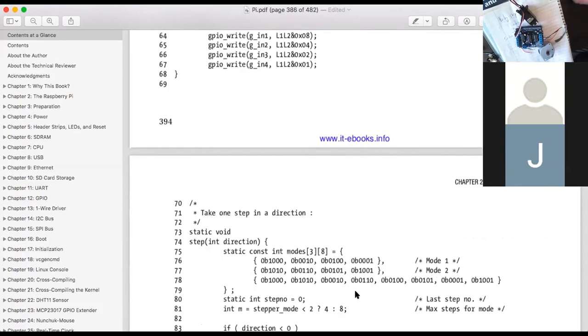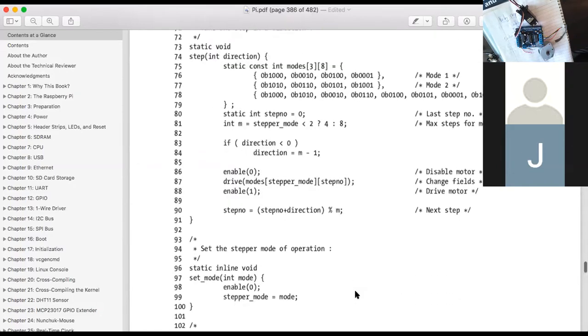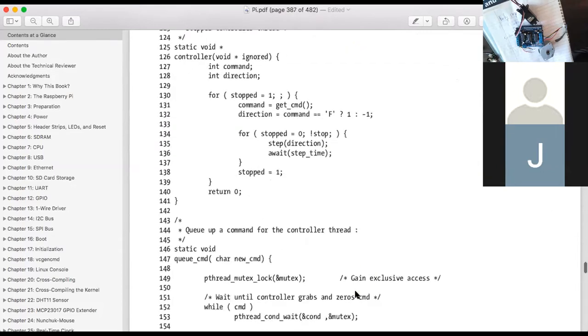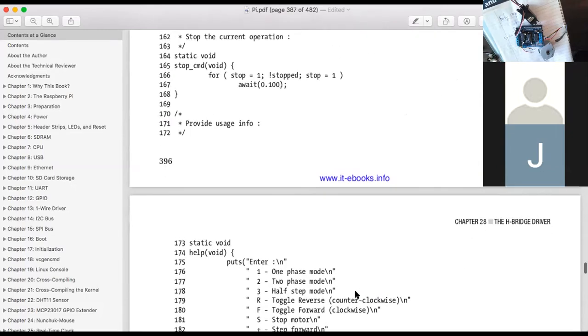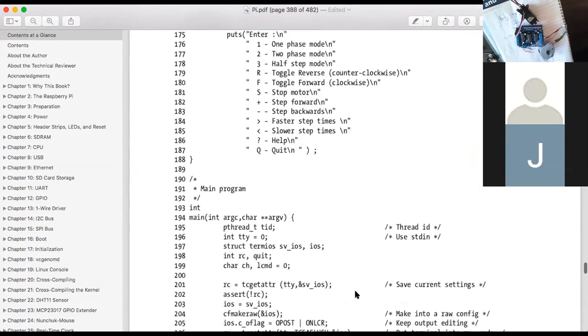How about cost? This one is very inexpensive. I think it costs less than $20. So if you have a project that needs H drives, it has 4 H drives and 2 servo drives. If you have a project that needs a couple of H drives to drive a DC motor or bipolar stepper, use one of these. This is called the Arduino motor drive. Just Google Arduino motor drive and you will find this. This is my favorite. It's wonderful. This is the Arduino motor drive V1 version.